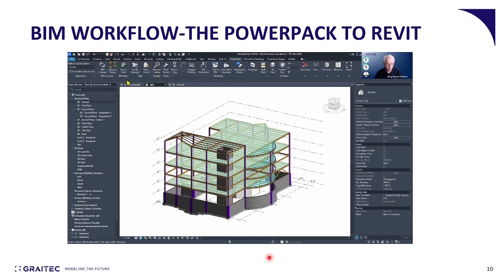And then, as I mentioned, we have got our very, very famous link to Excel. It's a bidirectional link. Obviously, you know that you can export a schedule to Excel, but when you do that with the Revit tools, that is a one-time opportunity. It's a snapshot in time. But if you use this tool, you can export your schedules out to Excel, make changes to that Excel, and then bring it back in to Revit. And those changes, if appropriate, you can review them. It will force the updates and make the updates happen.